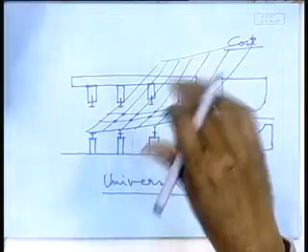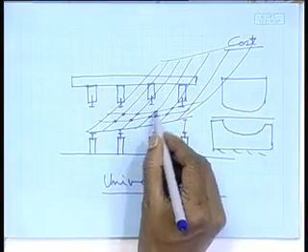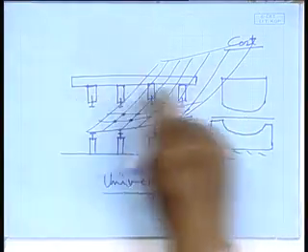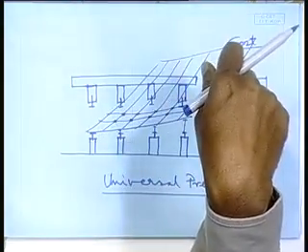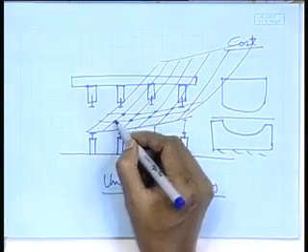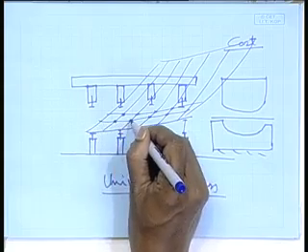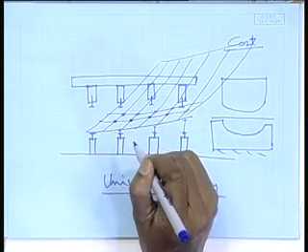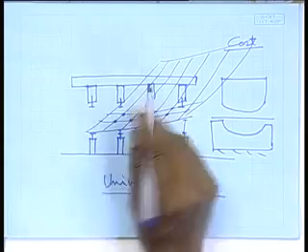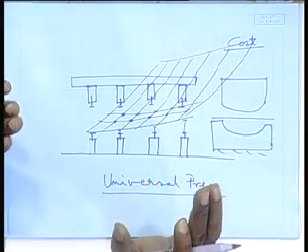Here, it cannot be just take a camera image and do; it can be done, but that will be tremendously computationally expensive and time consuming probably, because if you take a camera picture and extract this coordinate data, it could be difficult. Instead, a laser beam scanning is possible, and in a pre-programmed way it scans and takes only the z coordinates at predefined points, because the xy coordinates are well fixed, only the variation in the z coordinate I will measure.